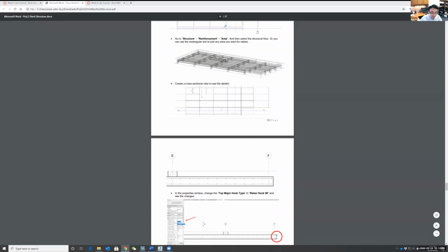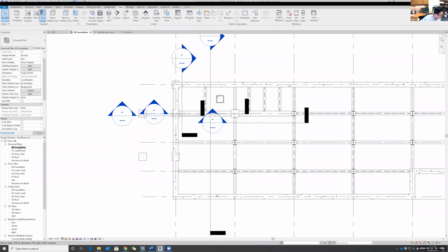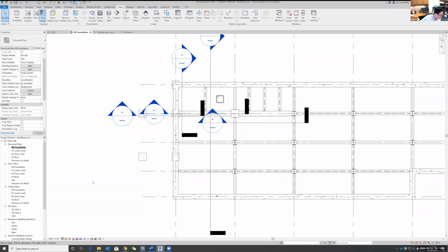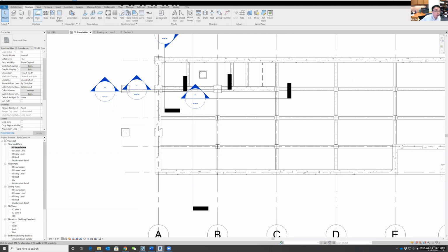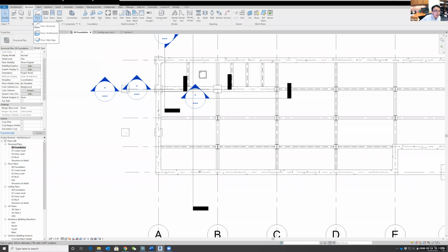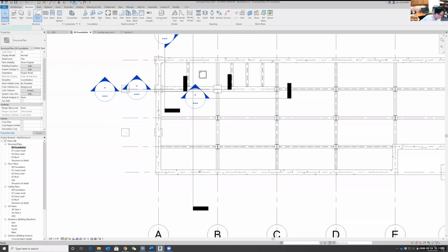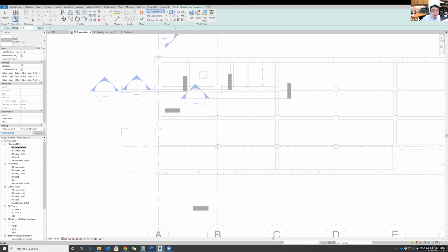All right, so let's go back to here, and let's go to item 7. So first, let's go to structure plan, 0 foundation. All right, here we are, and then go to structure, floor, and instead of clicking this floor directly, let's use the triangle and just say structural, floor structural. Okay, and now once we're here, let's use the rectangular box here to plot the floor.